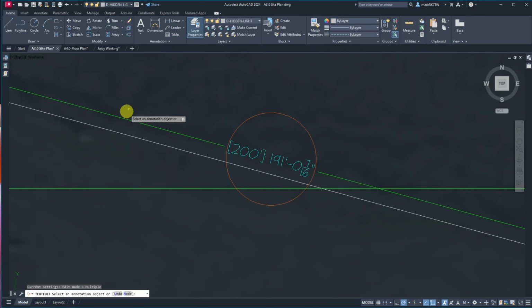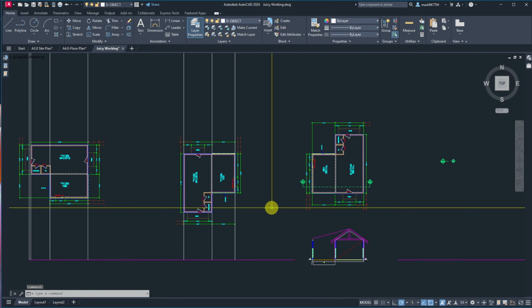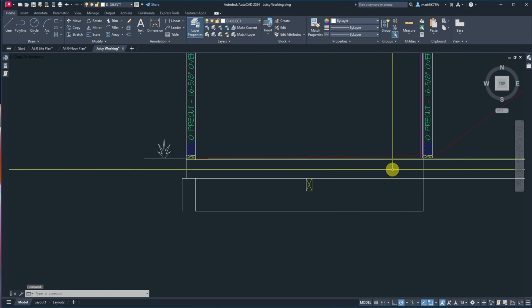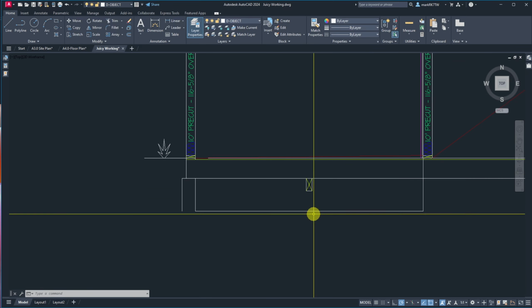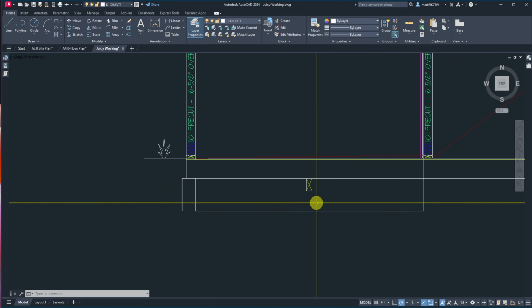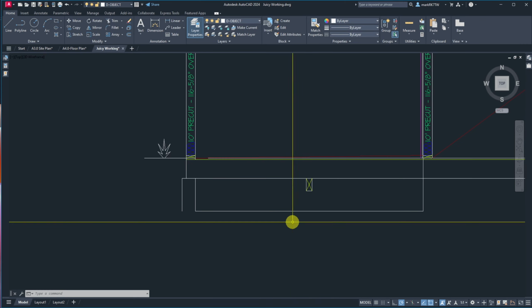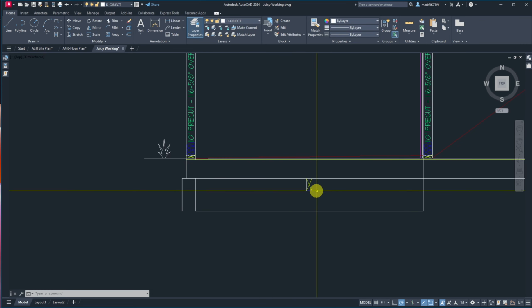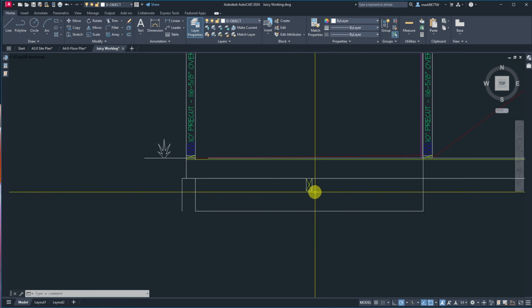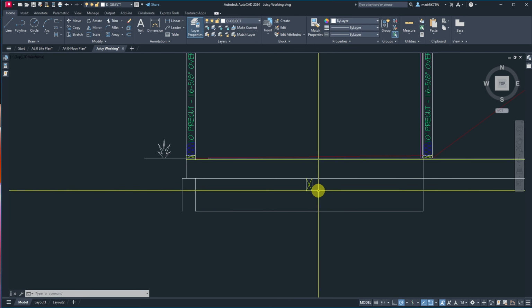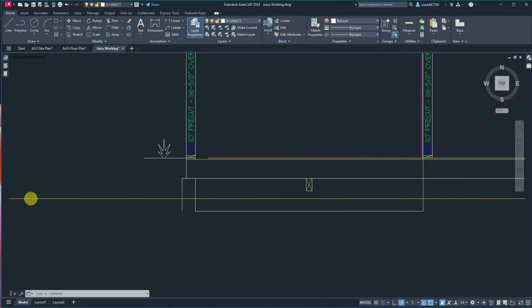That's really what I want to show you, along with the stuff that we need to discuss as far as how we're going to deal with this area, because wood needs to be 12 inches clear of soil. I will look that up and see if anything changed when we adopted 2021 from 2018, but I think that one probably stayed the same.